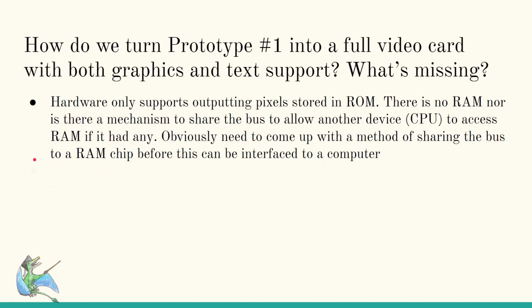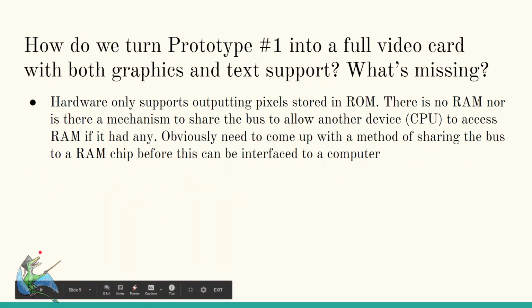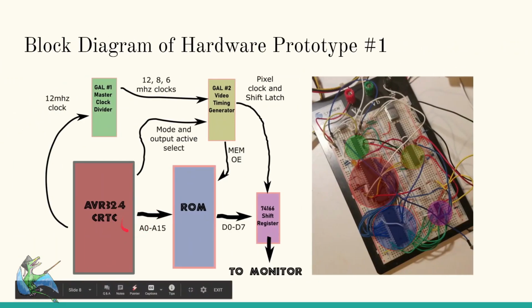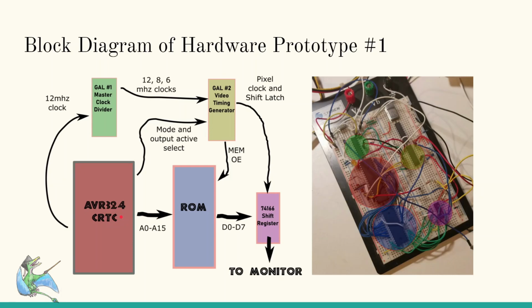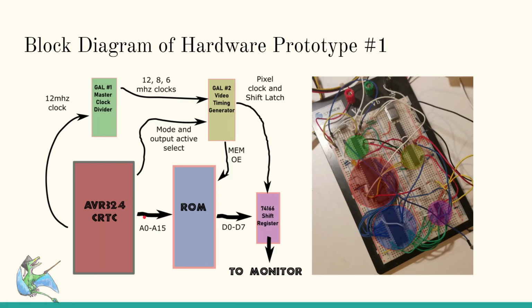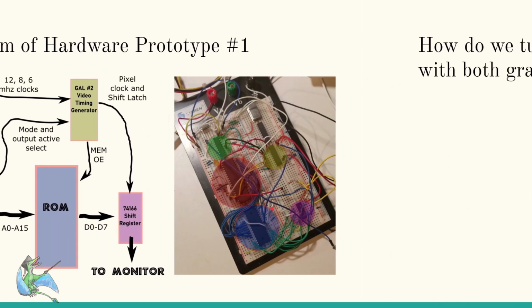So basically, if we go back to the previous picture, we've got a one-way address bus that goes from this, which is essentially the bus master, to the ROM. Well, the output ports on this chip are active all the time. So they're always driving the address lines of the ROM.